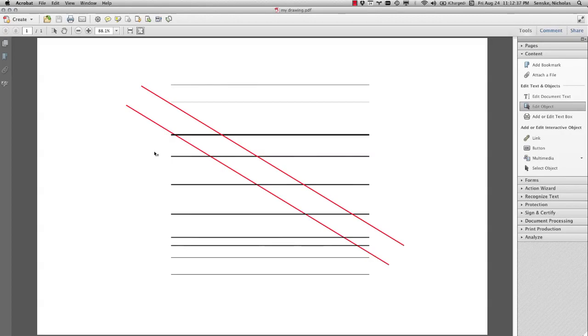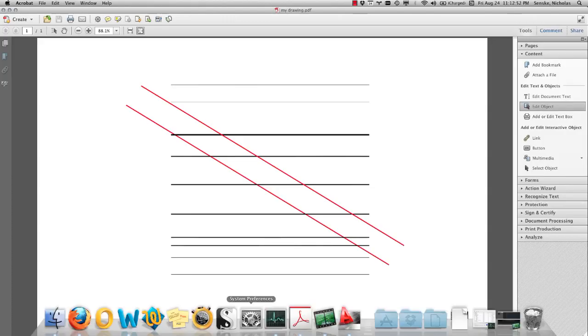Okay, and again, the line weights are built into the template, and we access them by choosing layers. We use the PDF layout and 11:17, and when we plot it, everything comes out fine. Okay, so that's the generic way to proceed through the assignment.